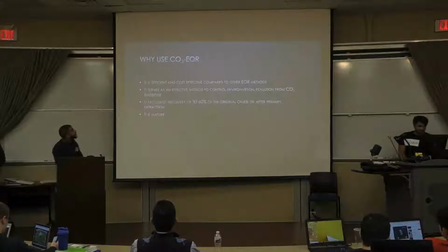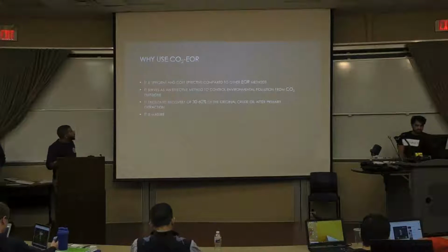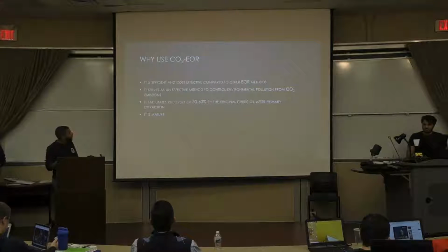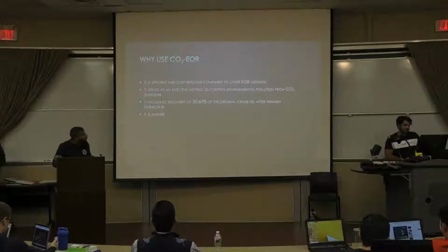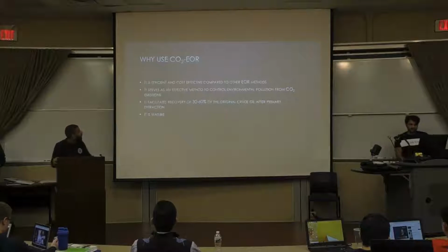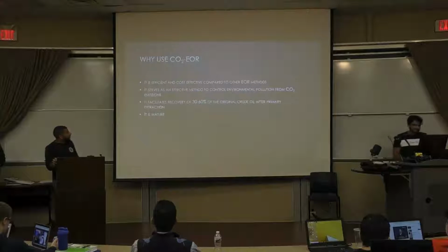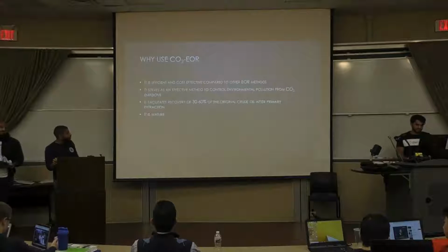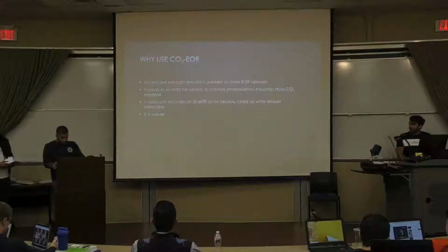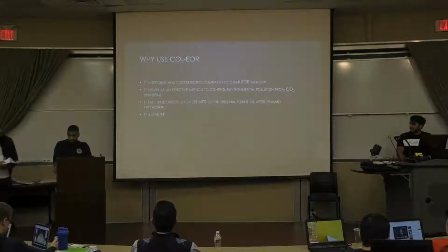Why do we use carbon dioxide? It is efficient and cost-effective compared to other EOR methods. It serves as an effective method to control environmental pollution from carbon dioxide emissions and facilitates recovery of 30 to 60% of the original crude oil after primary extraction. And it's a major technology since it has been in use for many years now.